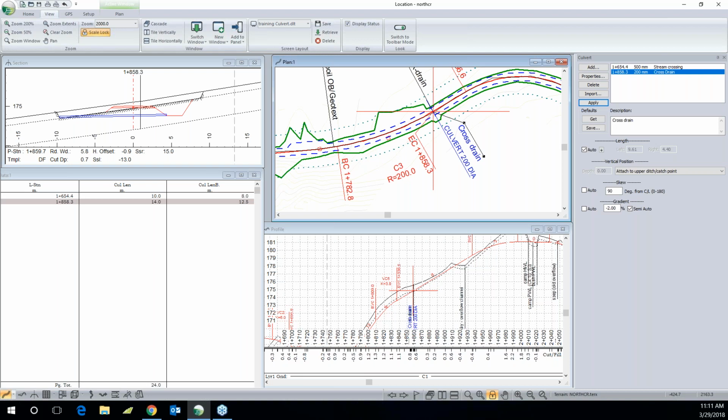Jack, when you get a chance, if you want to look at the question. Yeah, there's a question here. Just looking at the question for a second. The question is, is the minimum fill measured from the bottom of the road layers or from the top of the road? It's measured from the subgrade surface, the bottom of the road layer. I hope that answered your question. Okay.